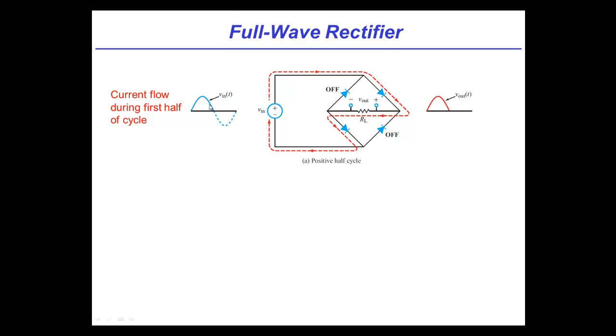Let's say I'm in the positive half cycle. Well, in the positive half cycle, which diode do you think, of these 2 diodes, let's call it the top left and the top right, is going to be on, Michelle? Well, remember from the last diagram, the check valve behavior, it goes from the back of the triangle into the triangle. It follows the arrowhead. Follows the arrow, exactly. So that means the positive current will want to follow the right diode, but it'll hit a roadblock on the left one. Exactly. So that'll be off.